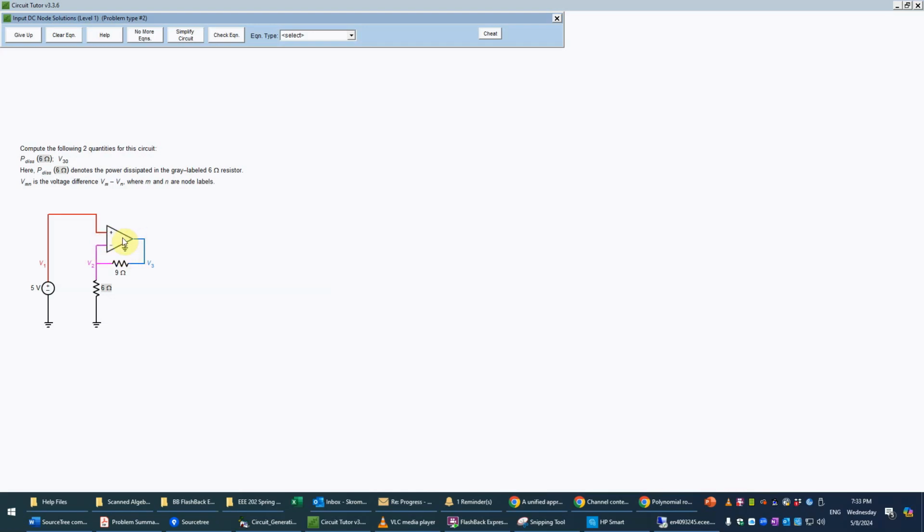And the output, of course, being the output of a voltage source, can be whatever it needs to be, at least in principle. So we might recognize this as, first of all, having proper negative feedback from the output back to the negative input, which you always need to have in an op amp circuit that's not, say, an oscillator or something like that, which isn't stable.